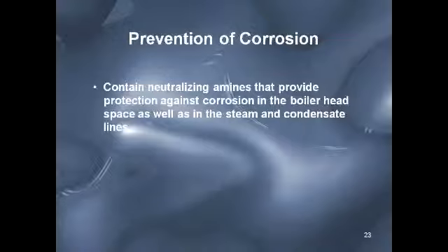Boiler water treatment should also have neutralizing amines. These will go with the steam and provide protection against corrosion in the boiler head space as well as in the steam and condensate lines.